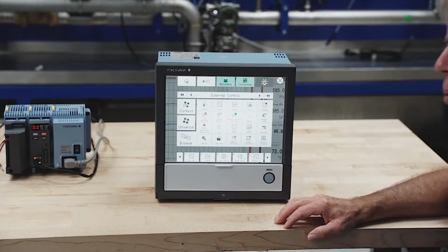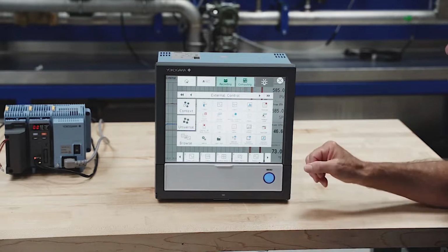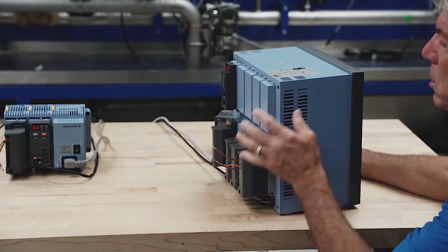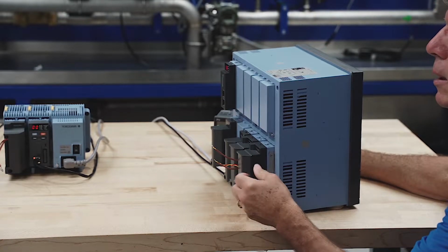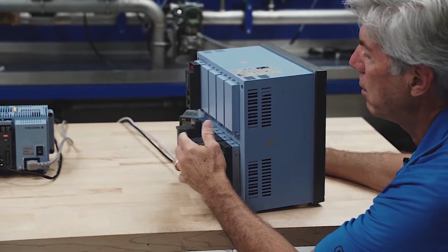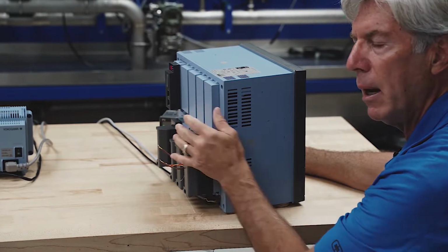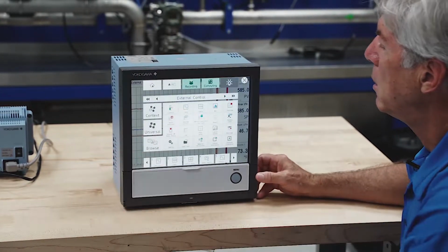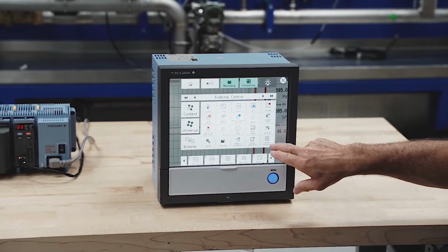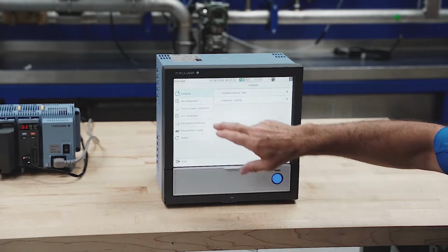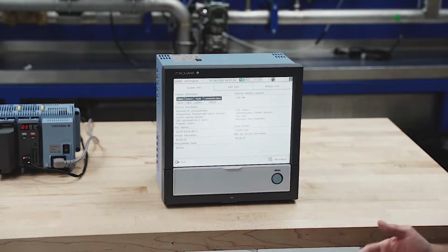A lot of these products are purchased in piece parts. What I mean by that is you might purchase a shell of a recorder with maybe one module, and then 6 months later, you might find the customer needs to add another couple or 3 modules. So when you add these modules, when you initially set up the hardware configuration, the best thing to do is go to the initialize calibration icon and go to reconfiguration, execute, and then let the recorder reconfigure itself.